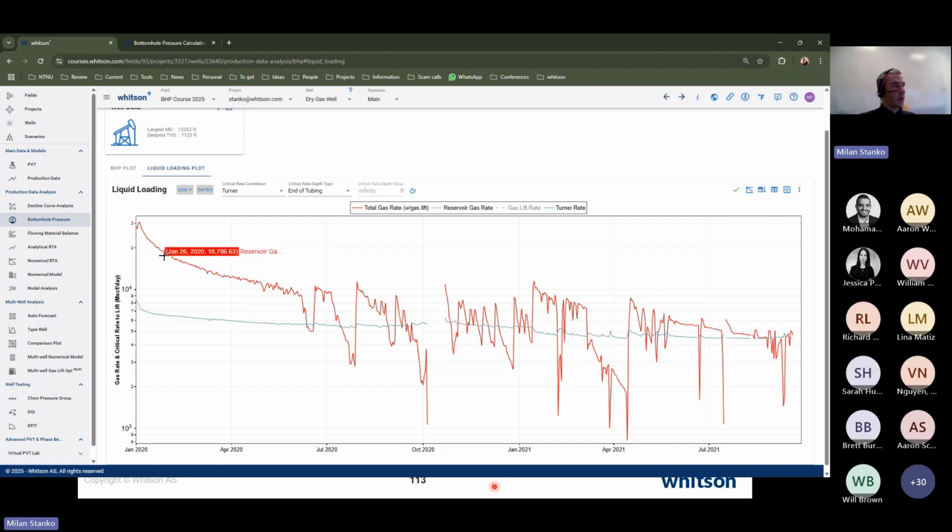Okay, so here it tells you that during the first period of production, everything was nice and healthy. But then at some point you went below, maybe temporarily, but then it went up again. Then it went down and up, and then suddenly you're getting closer and closer to that line. And you see your gas rate behavior is becoming more erratic. It's not declining smoothly like it's doing here, but it's going more and more erratic. And that's due to liquid loading. That is a sign that you're maybe entering into liquid loading and things are deteriorating quite quickly, and that is affecting the performance of your well.